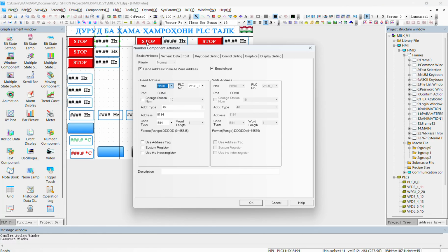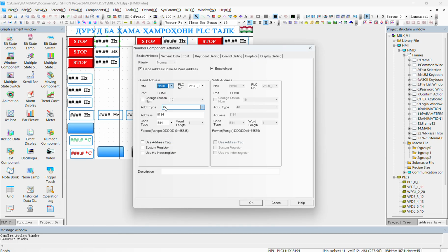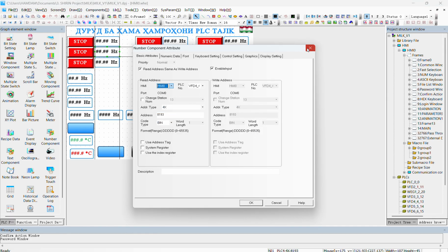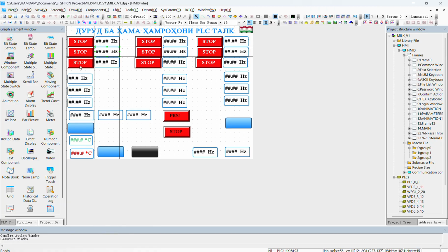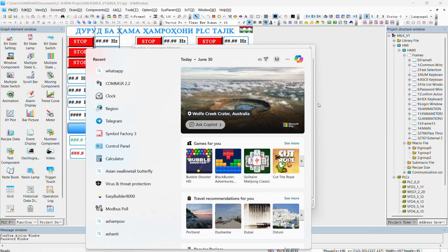This is a kind of address reading. Here you need to enter the address in decimal, not hex. Here I'm using a Delta VFD for operation, and for the frequency command I think the address is 2000 and 2001. I will just show you.